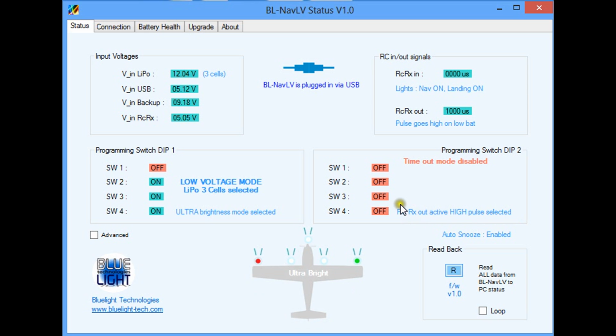Or if you set them both, for example, let's set a time here. I'm moving one of the dip switches here, and you can see I've set a time here of 10 minutes. And you see here, since both dip switches have been set up, then the warning sequence will happen based on whichever one happens first. So that's the main purpose of these dip switches.